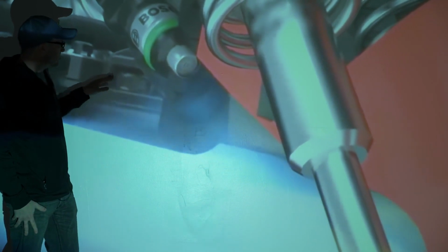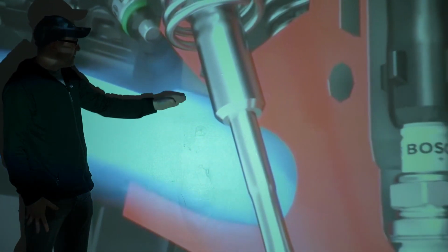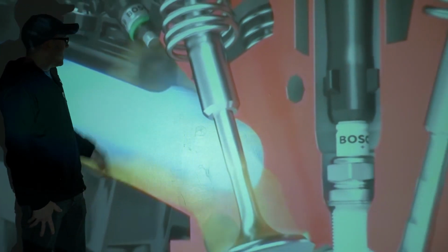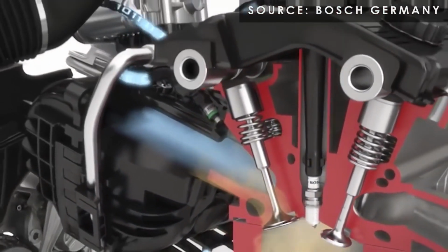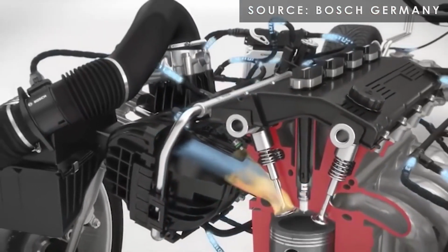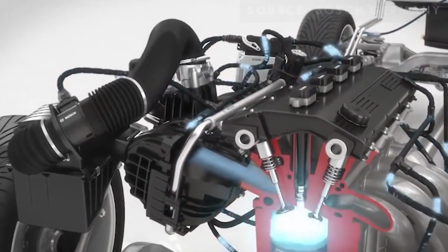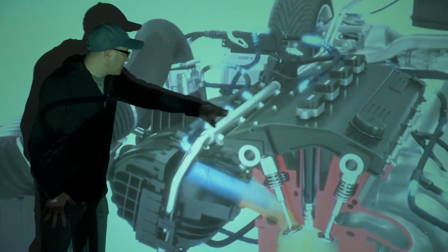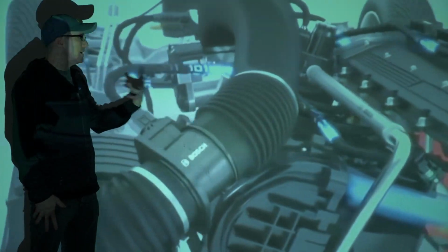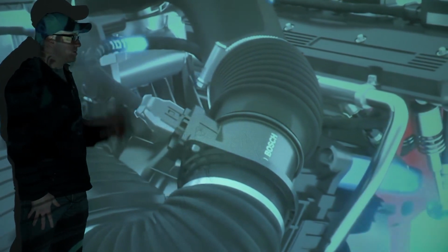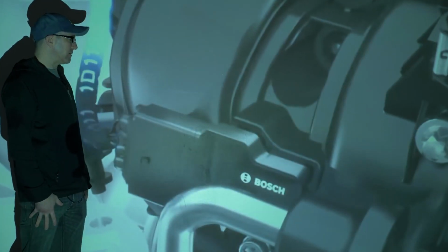But this time, instead of spraying directly into the cylinder, you're spraying on the back side of the valve train through the openings of the valve ports into the cylinder that way. So there is fuel constantly being sprayed on the backside of these valves. There is no injection into the cylinder directly. And you can see the way that the fuel flows here. Also, you do not have a high pressure system that's cam actuated to build it up. So you only have one fuel pump for port injected cars, which simplifies the process quite a bit.